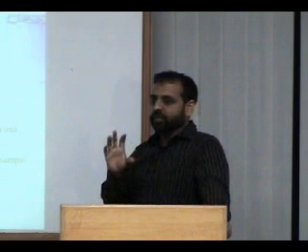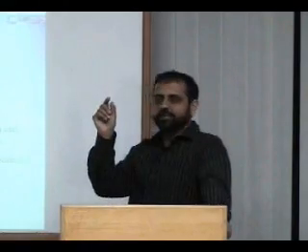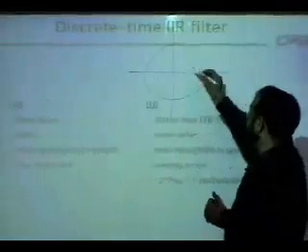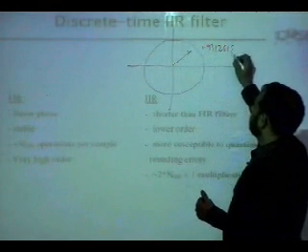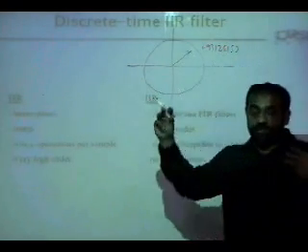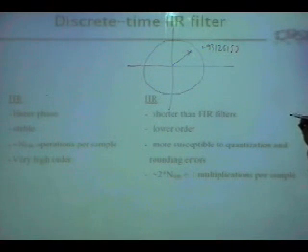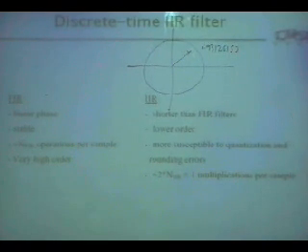Quantization means if you are quantizing your coefficient to 8-bit, the pole will change its position. If you have infinite precision, you design a filter in MATLAB, in double precision arithmetic, it tells you the pole is at 0.93126157. It's a double precision floating point number. But if you are using a DSP which is only 16-bit, remember those of you who have taken the course, you need to change it into Q format. So you truncate it, you only keep 16 bits.